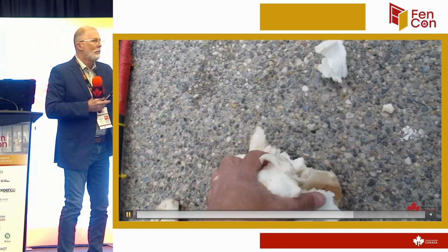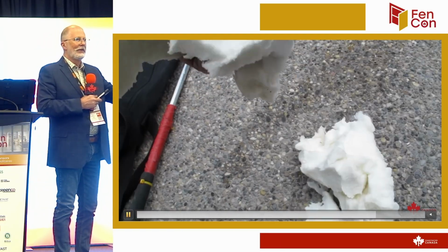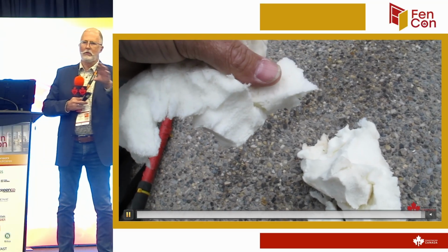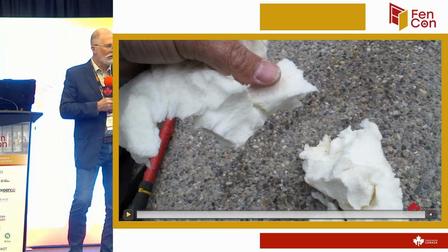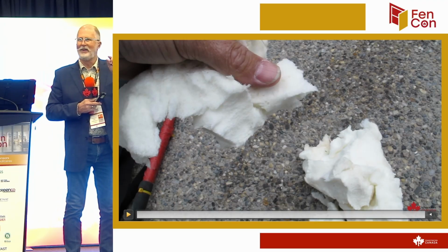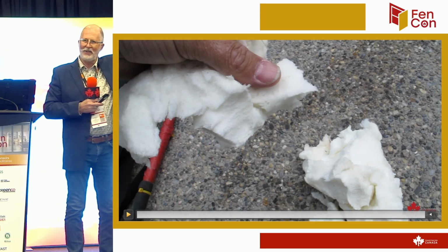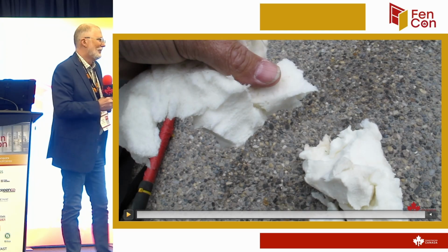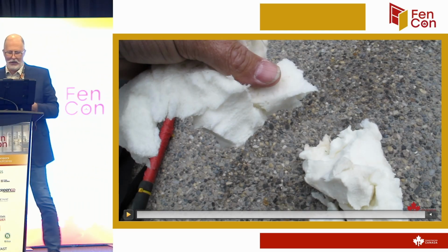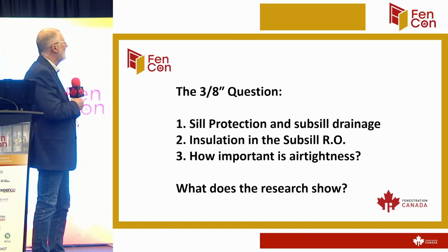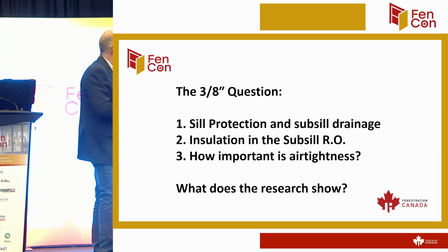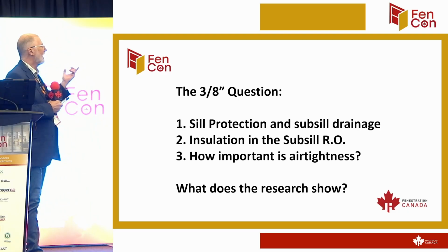They resist that water. But if you cut the skin, does that still occur? In other words, you do all the things you're supposed to do correctly, and that foam's hanging out a quarter of an inch, and the finishing carpenter comes along, and he can't deal with that, so he cuts that face off and trims the window out. Is that going to soak up some of that moisture, right? So those are the risks that we look at when we look at all materials in the building. So this comes back to that question we started off with at the beginning, the 3/8 inch question.